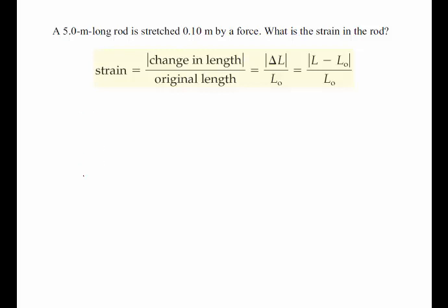So here we have our ability to calculate just this very thing, strain. So we have a rod that starts off initially 5 meters long. And then it's stretched by some force that we don't know, so we can't figure out the stress, only the strain. And it's stretched an amount, delta L, of 0.10 meters. And we want to know the strain on the rod, and so we're just going to use the above equation so that my strain is the change in length